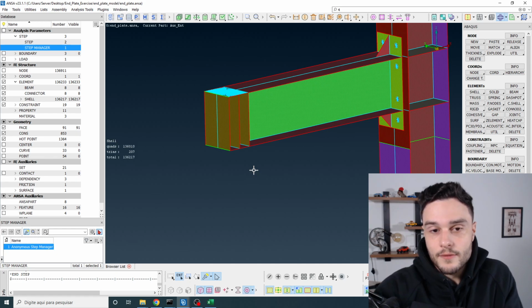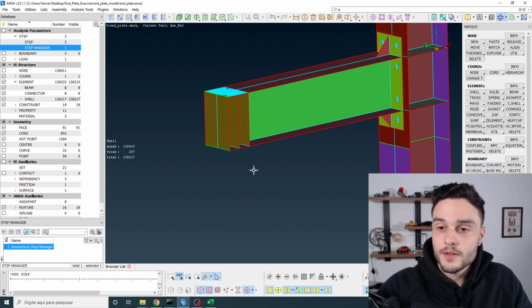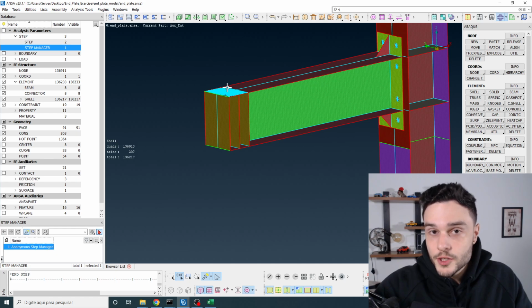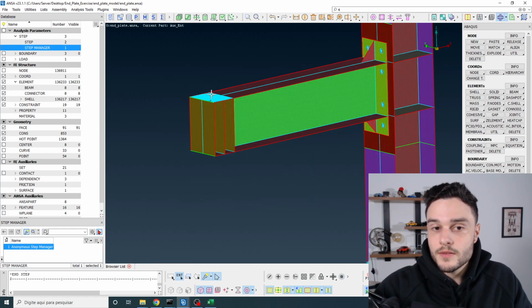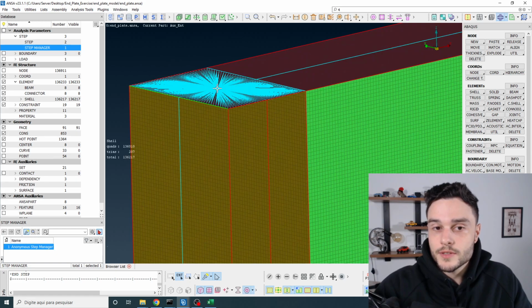And then, after the software calculates the active displacements, we can use this result in the constraint equations that have the reaction forces, and then we can calculate the reaction force. Well, in a nutshell, we are going to be able to calculate the force that we have acting in the downward direction at this node.